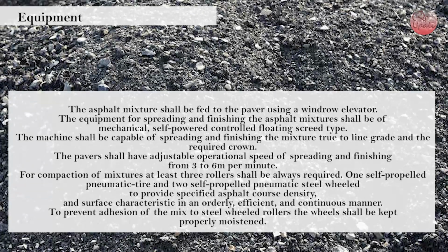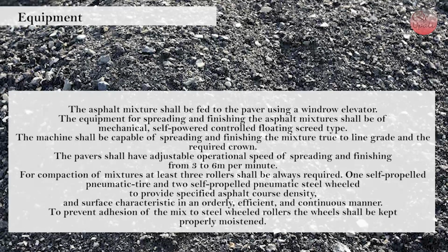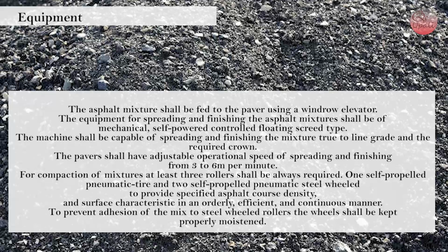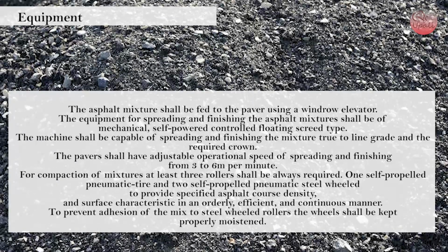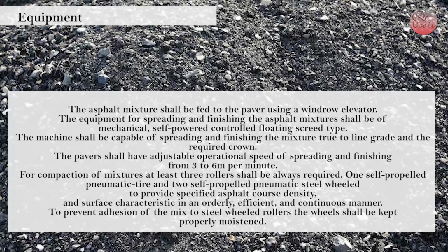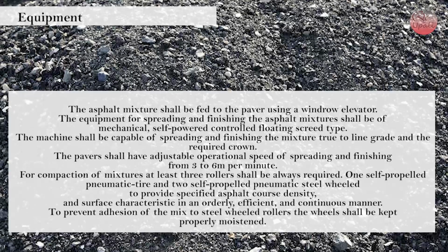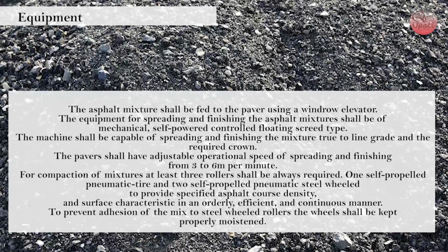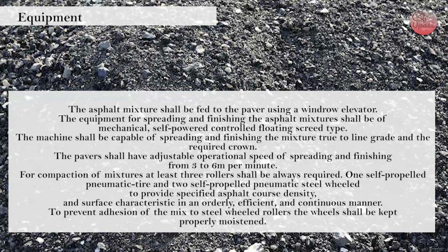1 self-propelled pneumatic tire and 2 self-propelled steel wheel rollers to provide specified asphalt course density and surface characteristic in an orderly, efficient and continuous manner. To prevent adhesion of the mix to steel wheel rollers, the wheels shall be kept properly moistened.